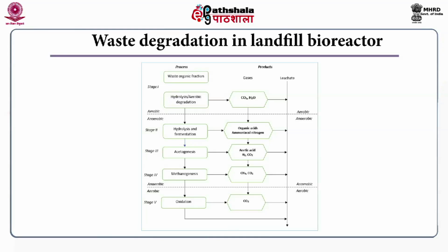If you see, during aerobic degradation, you can observe carbon dioxide and water being produced, and in hydrolysis and fermentation you can find organic acids and ammoniacal nitrogen. In acidogenesis you have acetic acid, hydrogen and carbon dioxide generation, and in methanogenesis you have methane and carbon dioxide generation, and finally in the oxidation phase you have CO2 generation. So, these are the 5 phases of degradation of waste within a landfill bioreactor.